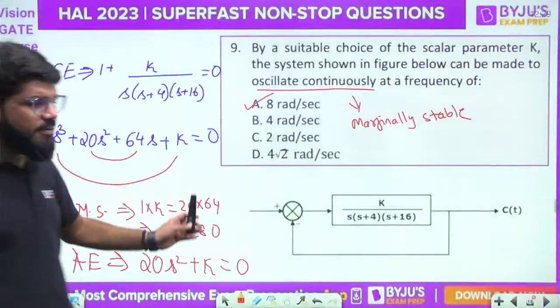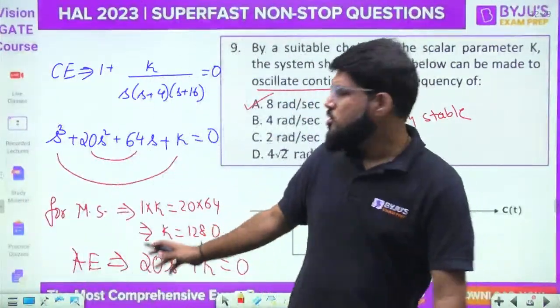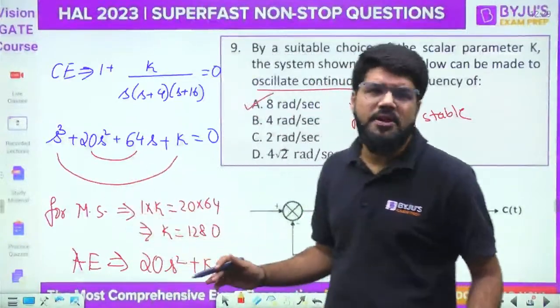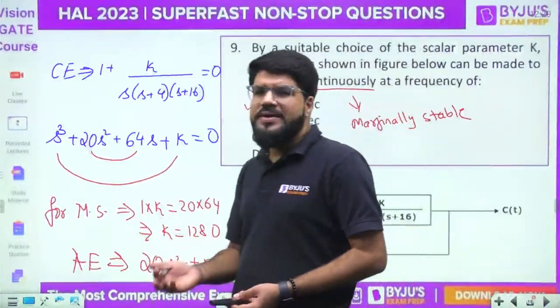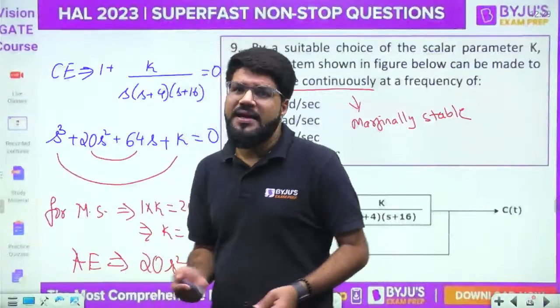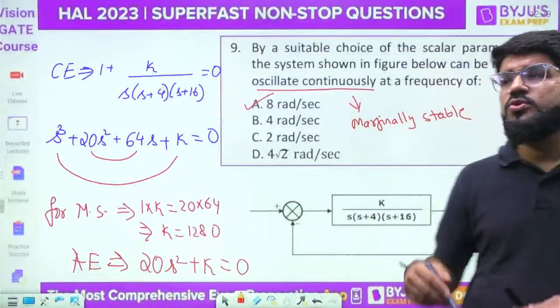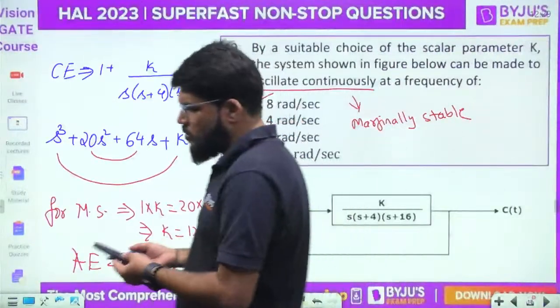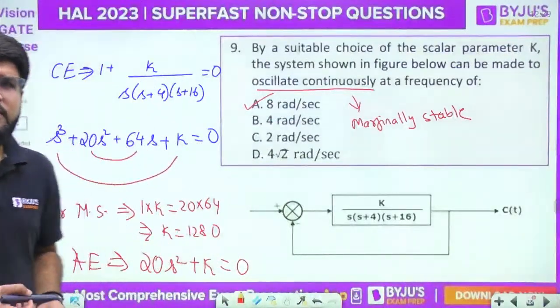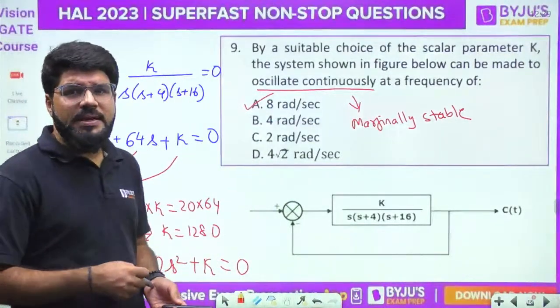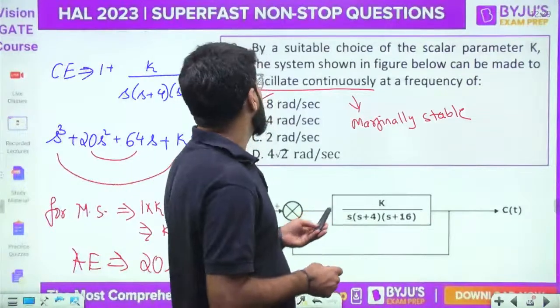Otherwise, you can also solve it by the complete Routh array if you're not aware of the shortcut, but it is cubic. Better to remember the shortcut because questions on cubics commonly come, directly or indirectly. Sometimes it's also useful for calculation in root locus indirect problems. So you should know about this. Yes, Martina, correct answer. Moving ahead to the next one.